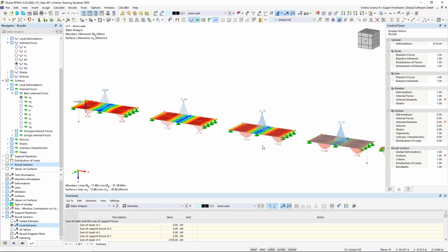So as a rule for you to keep in mind, the best way to create an FE mesh is to hold it as fine as necessary, but at the same time as coarse as possible, because these are the two opposites you need to weigh up between the precision and economical aspects of your work as an engineer.